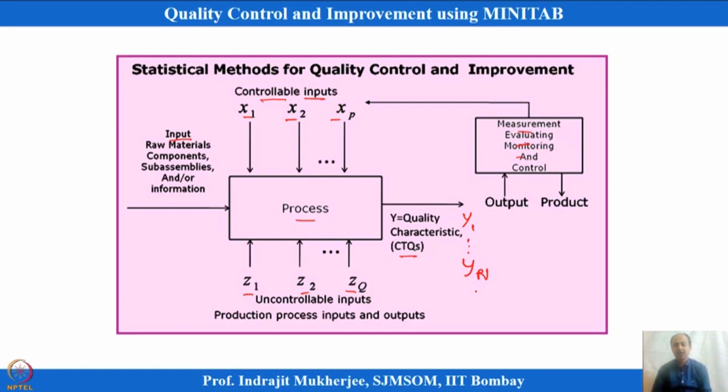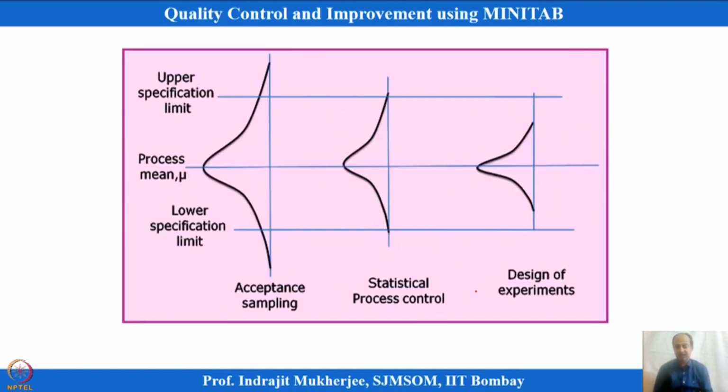Okay. Now, for monitoring and visualization we can take data from the process and draw histograms, but a histogram is not suitable because there is a time dimension. According to time, process characteristics change, or when we change the shift, person-to-person variation happens and the setting condition changes. So time is an important dimension which needs to be considered, and a histogram does not consider it. So we need something else to monitor the CTQs with respect to time. Statisticians came up with a solution, which is known as the statistical process control chart.